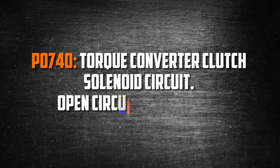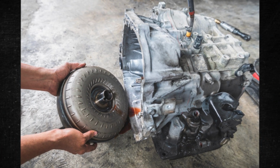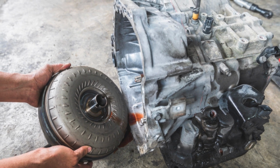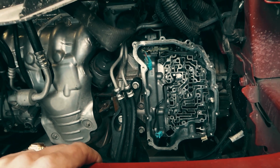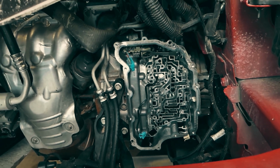P0740 Torque Converter Clutch Solenoid Circuit. Open circuit malfunction. The Powertrain Control Module detected an abnormal reading from the torque converter clutch circuit, according to the P0740 trouble code. The PCM typically undergoes a number of checks, and before the light illuminates, the reading must be abnormal for a predetermined period of time.